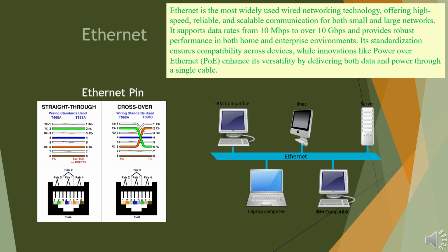Ethernet also offers long-distance capability. Unlike short-range protocols like I2C or SPI, Ethernet can span up to 100 meters using twisted pair cables, Cat5e, Cat6, or much farther with fiber optics. This makes it ideal for large-scale mechatronic systems, smart factories, and remote sensing networks. Another major advantage is reliability. Ethernet uses error detection via CRC checks and automatic retransmission to ensure that data arrives correctly. Modern network switches further isolate communication paths, preventing collisions and ensuring stable, full-duplex data transfer.